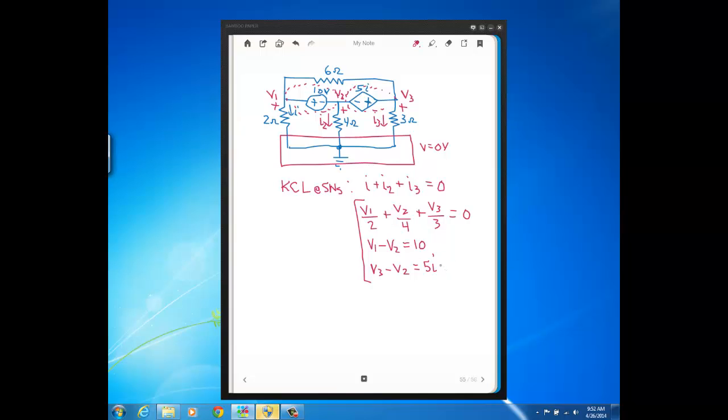Okay, so now looking at our 3 equations, look, now we've got 4 unknowns and 3 equations, right? Because that dependent voltage source introduced this new variable as part of our node voltage expressions. So I need to now write the current that the dependent source value depends on in terms of what we're solving for, and we're solving for node voltages. So that's when we look at where I is defined. Well, I is defined right here. It's the current through this 2 ohm resistor.